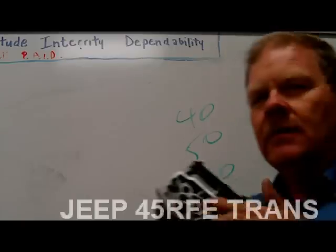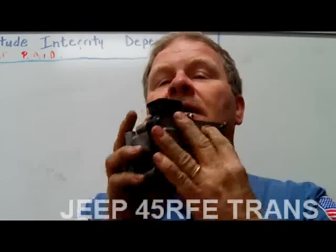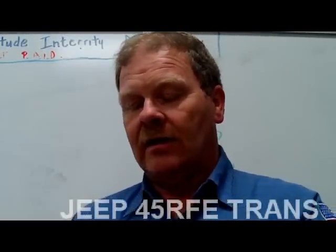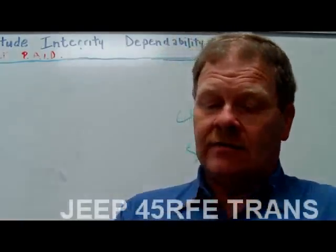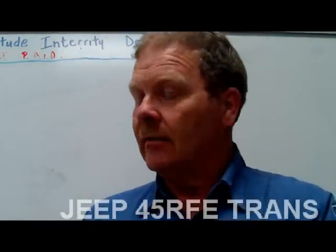Yeah, that's right. That is bolted right on the front of the transmission. It's got this little computer with it, and those little solenoids are in there. See what I'm saying? It's got the bolts right here, three bolts right there. And I've actually got the cover off so you can see it. It ain't got that many wires going to it. But you've got to get the right one for that vehicle. And of course, they've got a big sign on the front that says removing the cover can alter calibration, replace, do not repair.